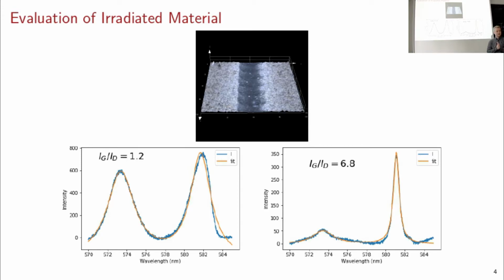The other way to measure this, and what we're really interested in, is resistance. So we want to be able to create conductive lines. That turns out to be much more difficult from a technical perspective because we can't do that with the laser. So that involves taking the sample out of this machinery that you saw before and putting silver ink pads at the end of the lines that we drew, and then measuring the resistance there. So this needs to go into a separate piece of machinery. After that, we can't easily put it back because of alignment issues and stuff like that.